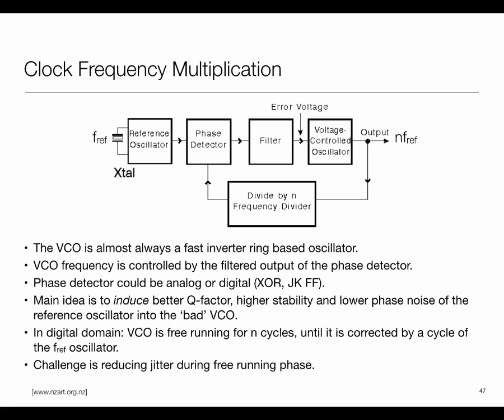There are many easy ways of doing this. Even quartz crystal oscillators can act that way, but there are simple circuits where the voltage affects the frequency. This thing could be unstable. But the main thing is, we design the voltage controlled oscillator such that it is seeking to produce a high frequency clock.